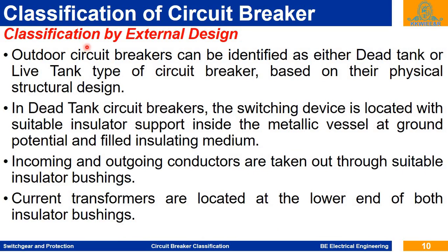Then the next classification is based on the external design of the circuit breaker. This is for the outdoor type circuit breaker. This external design classification means dead tank or live tank circuit breaker. It is only for outdoor type circuit breakers. Outdoor circuit breakers can be identified as either dead tank or live tank type based on their physical structural design, meaning the construction, how they are constructed, how they are mounted.